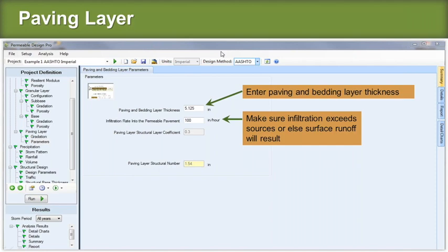And so in this case, a normal permeable pavement will handle 100 inches an hour. There is no storm in North America that's 100 inches an hour. You know, I keep mentioning Houston because they recently changed their numbers, but you get 14, 16 inches of rain in 24 hours. So all permeable pavements, take a bucket, throw it in the air, it comes down, it's gone. I mean, they're extremely permeable. With time, though, they could reduce their permeability.